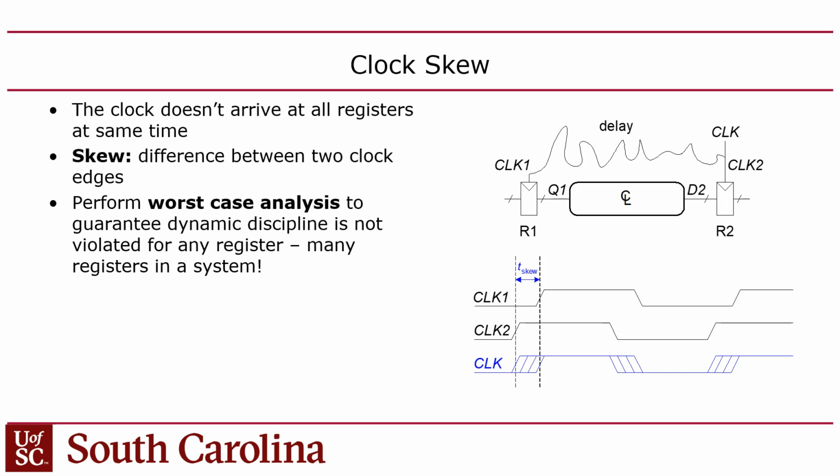By which I really mean, if the source is phase shifted positively relative to the destination, that effectively lowers the clock period. It shortens the clock period, because the left side of the clock period will be late relative to the right side, so it'll squeeze the clock period. So you have to build in the clock skew, which is the maximum shrinkage of the clock period due to skew. You have to add that as another term when you calculate. You guys with me? Make sense?